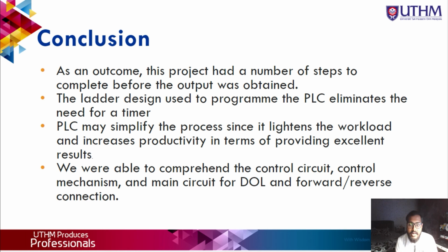The forward-reverse connection comes next, and consists of two contactors, one for forward and another for reverse, while we just use one contactor for the direct online starter. For forward and reverse, the direction of the motor will be affected by the connection. Each change of direction will have a time gap set by the timer. The ladder diagram used to program the PLC eliminates the need for a timer, allowing the PLC to control the changes.